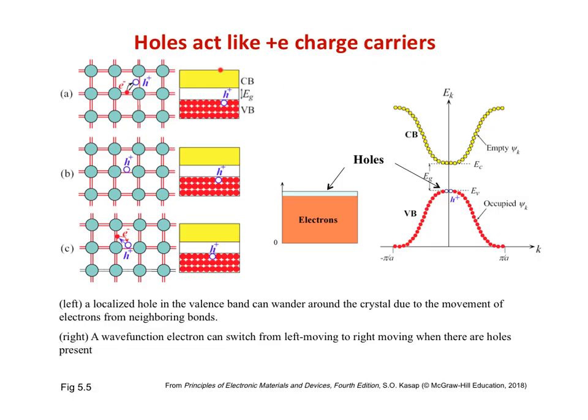In our block band diagrams, because electrons prefer to be lower in energy, the holes will appear at the top of the band. We can also think of holes at the top of the valence band as having virtually no energy penalty to move from right moving states to left moving states, therefore allowing electrical conduction. But because a hole in the right moving states is actually an extra electron in the left moving states, the effect of a hole in the right moving states is that of a positive charge moving to the right.